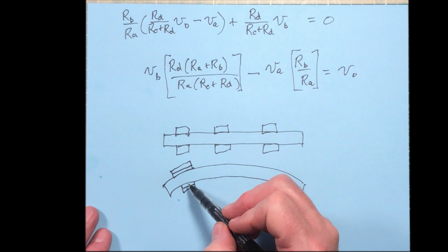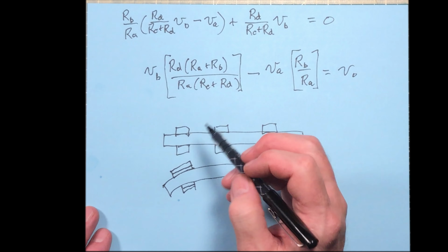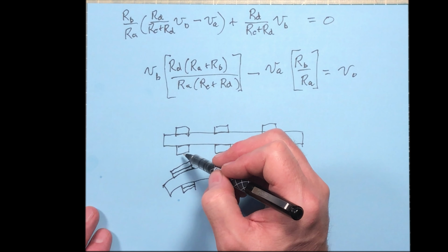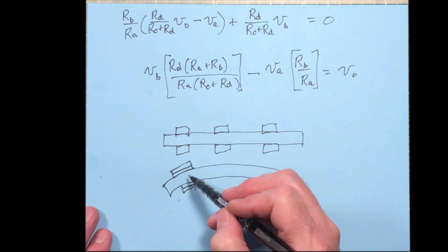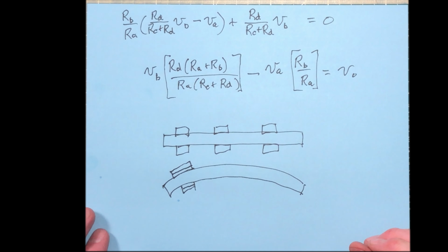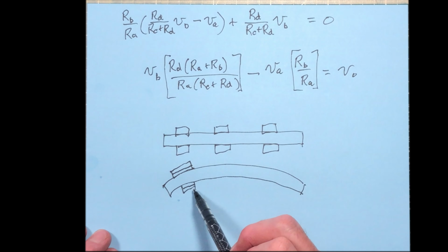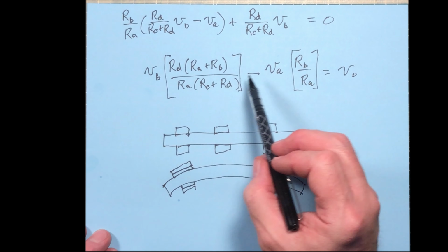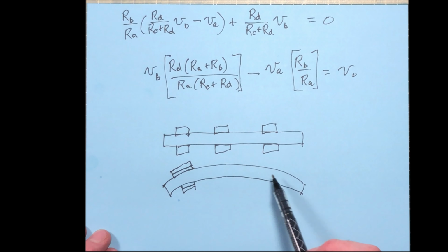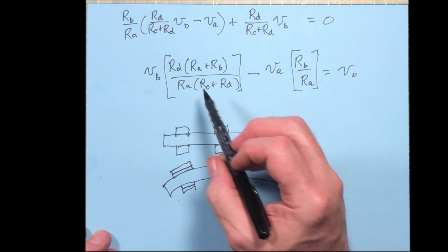So the resistances of those two wires right there are going to be different. But if they had exactly the same voltages passing through them, now they have different resistances there. So you're going to have a difference in voltage between these two. By setting these up and carefully monitoring what V sub A and V sub B are, as the resistances through these things change, then you can tell what the strain is on this, or how much it's flexed. And that's, like I said, the basis of a strain gauge.